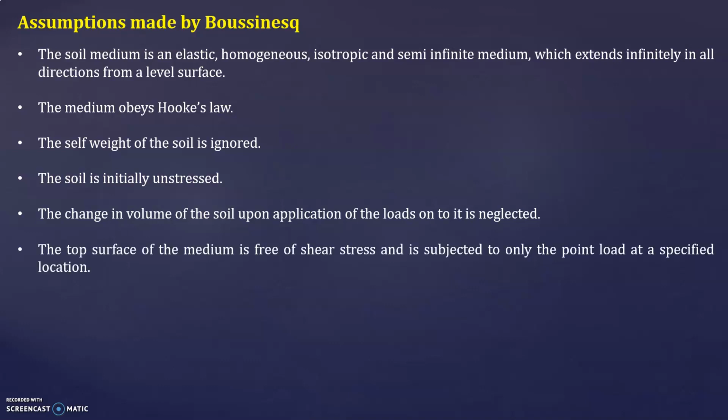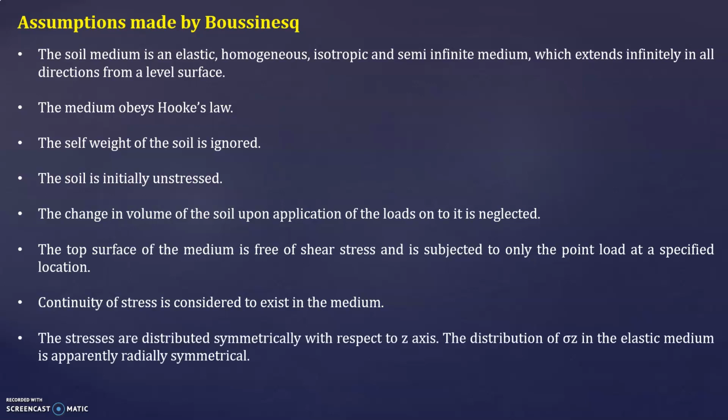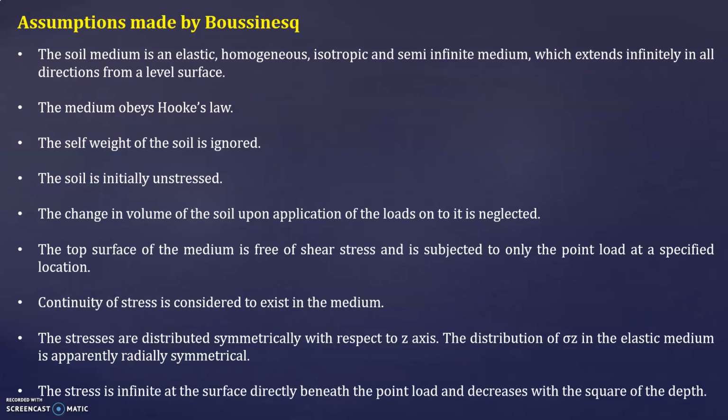The top surface of the medium is free of shear stress and is subjected to only the point load at a specified location. Continuity of stress is considered to exist in the medium. The stresses are distributed symmetrically with respect to the z-axis. The distribution of sigma z in the elastic medium is apparently radially symmetrical. The stress is infinite at the surface directly beneath the point load and decreases with the square of the depth. These are some of the assumptions made by Boussinesq.